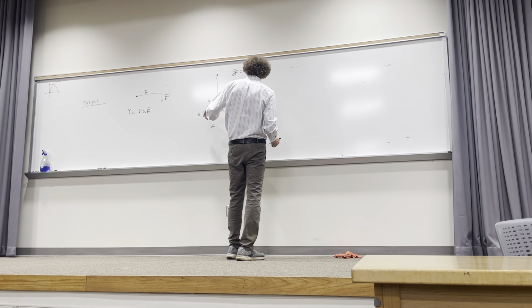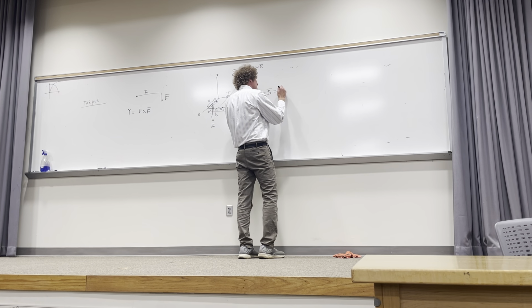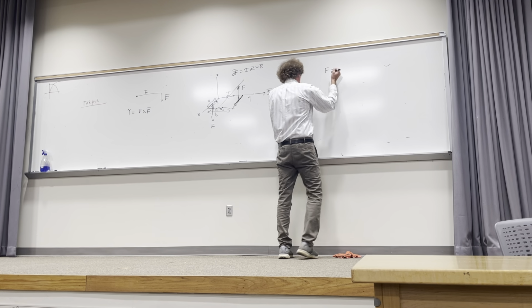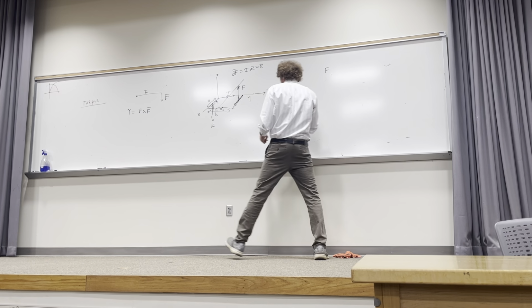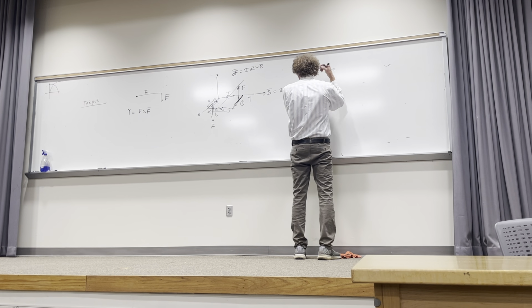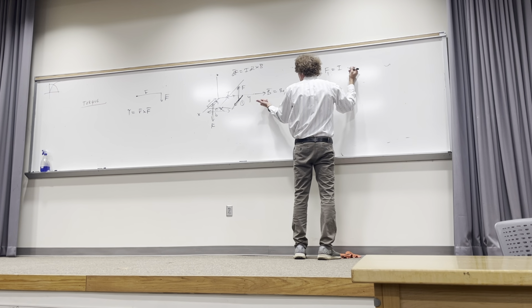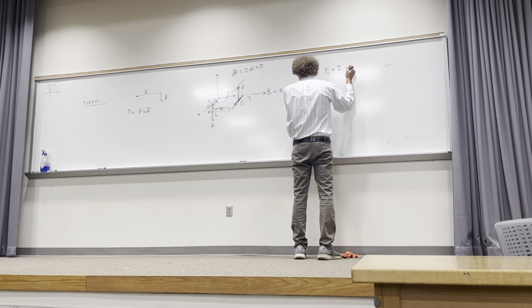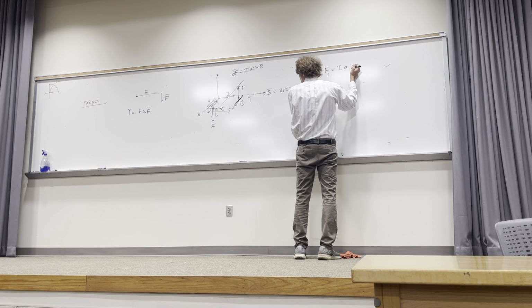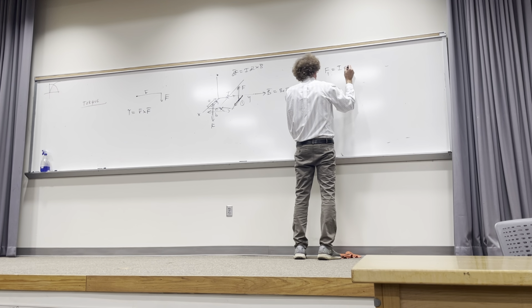If I've got that coordinate system, X, Y, and Z, the B field's going out there, so I'll just say that's equal to some B0 AY. Then I can say the force right there, I'll just say this member, call it 1, would be equal to I times L. We really don't need a differential here, so it's going to be I, whatever it is, times L. And L here has a magnitude length of A. That's what this side's length is. It would be in the AX direction.